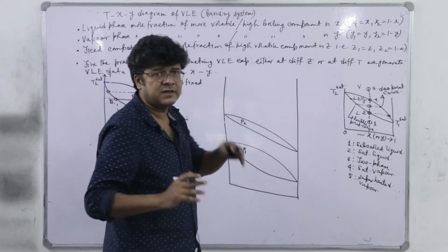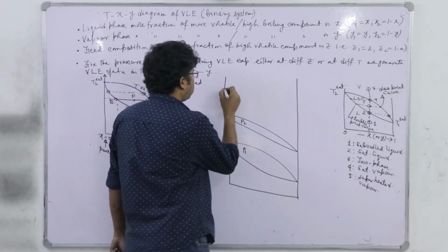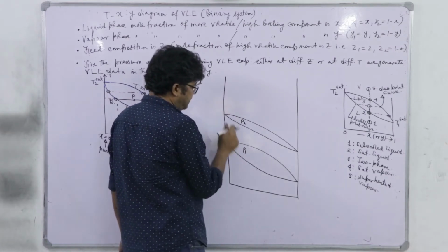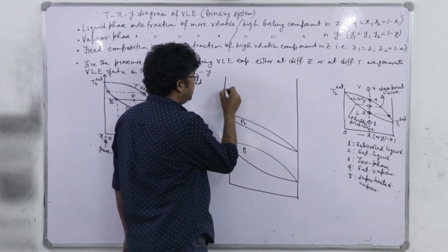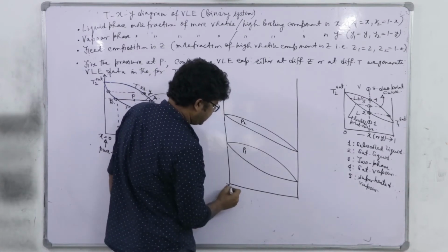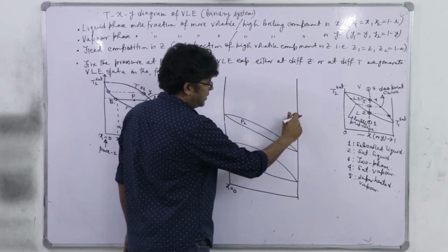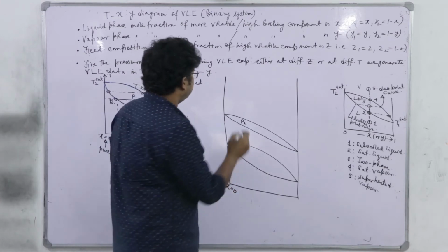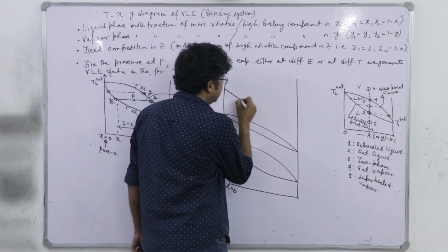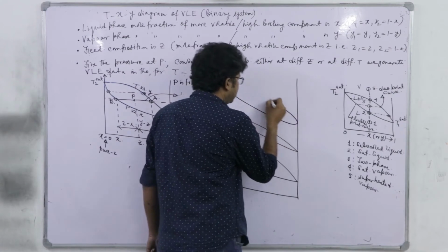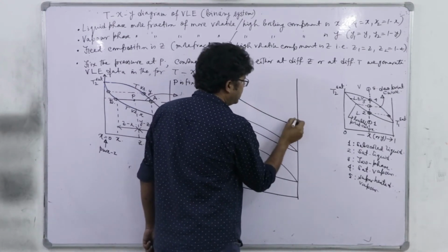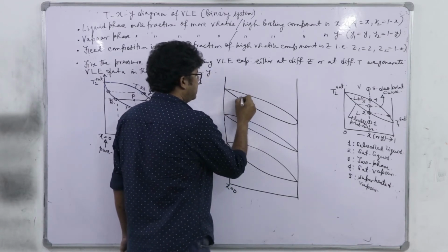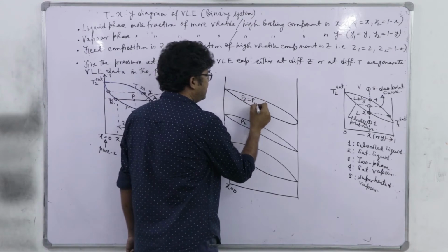Next, say we have reached the critical pressure of component 1. So what will happen? Here we have a point of derivative discontinuity. The derivative discontinuity will be maintained at x equal to 0. However, here it will be a smooth curve, which means it is at the verge of separation. See what happens. It will be narrowed down, definitely, right. So P3 is equal to P1 sat.